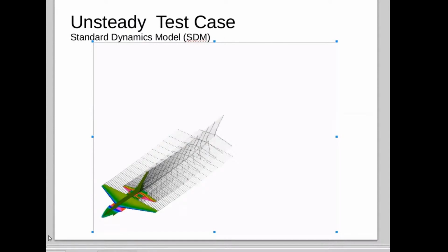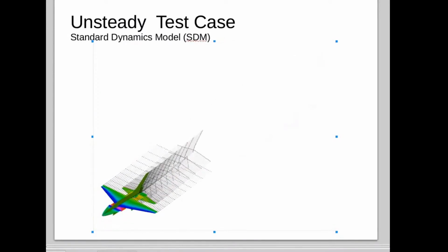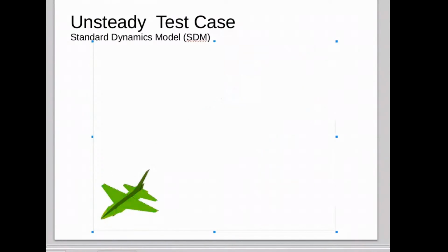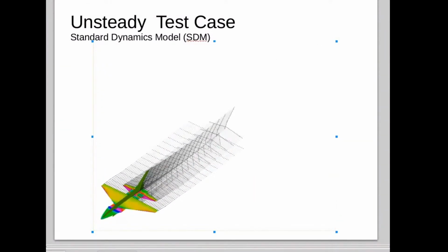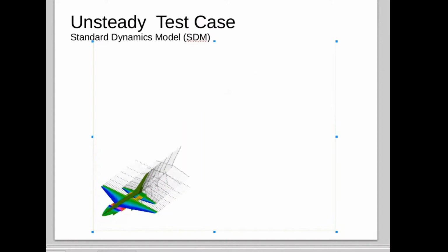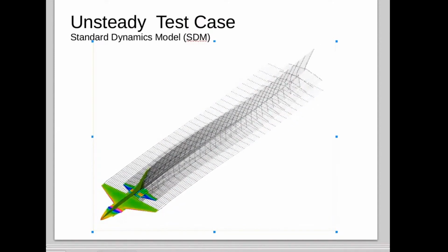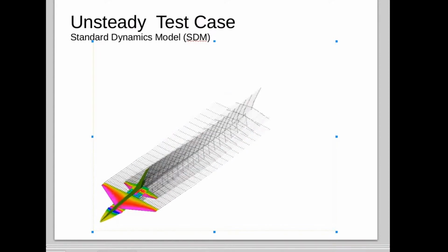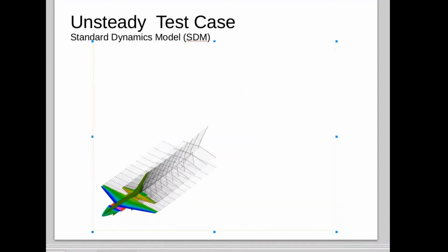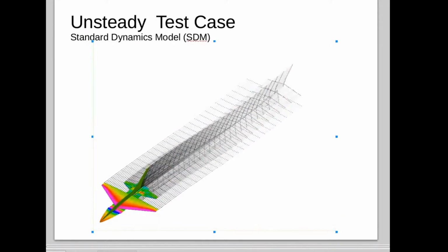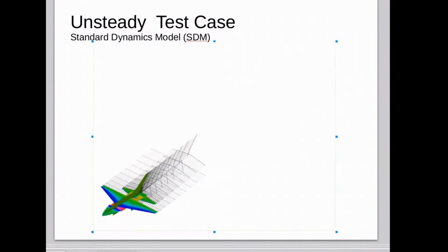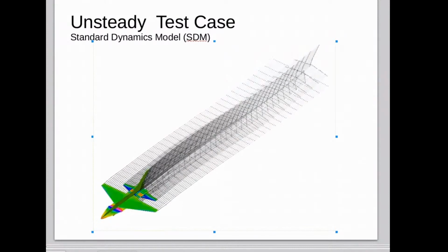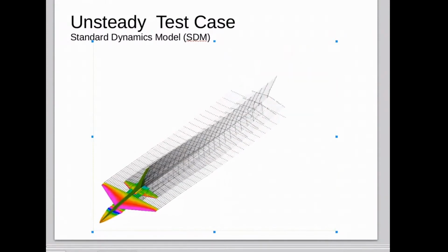And then if this will run. So this is just a repeat loop. Basically, it's doing a pitch up, pitch down. It's doing one full cycle of that to capture basically the unsteady behavior. Look at things, lift, drag, and moment as a function of time and obviously angle of attack. So using that data from this short analysis, we can basically back out things like CM alpha dot plus CMQ.